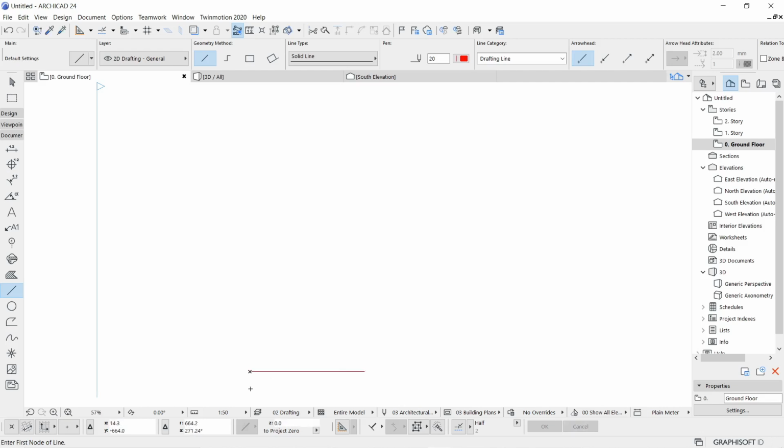If you now keep your mouse wheel button pressed and zoom in, you can see this is how you have drawn your first segment by using the absolute data entry method. That is, with respect to 0 you have done the data entry. Got the point? Okay. To check whether we have drawn this correctly or not, there are two possibilities. Now remember, in ArchiCAD, a command never gets closed. So my line tool is still activated and I can draw the next segment. But instead of drafting the next segment, I just want to cross-check what I have drawn, whether it's correct for its length or not.